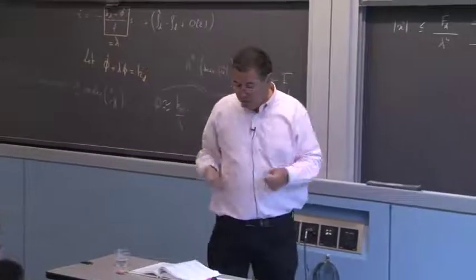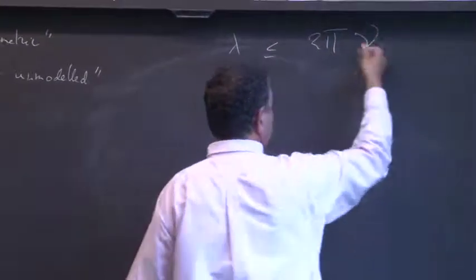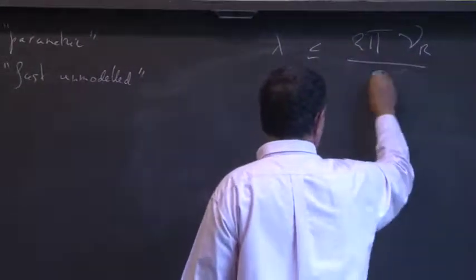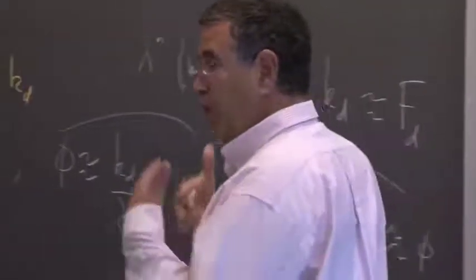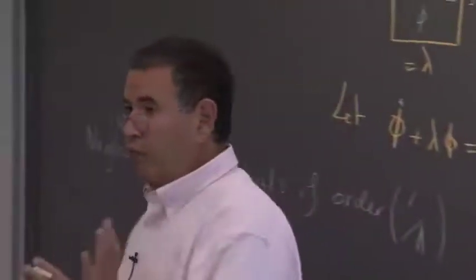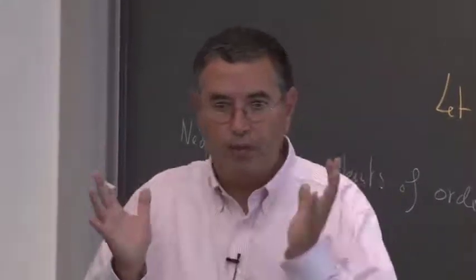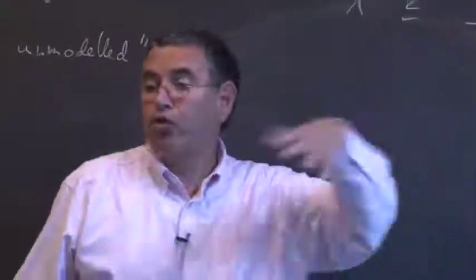And so you have a frequency in hertz of the first flexible mode, nu sub r. It's in hertz, so you have a factor 2 pi, and let's say you divide by 3. So nu sub r would be the frequency of the first unmodeled vibration mode, and you want, with the right units, to be within a factor of 3 or 5.